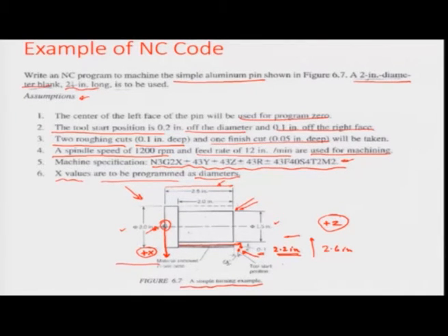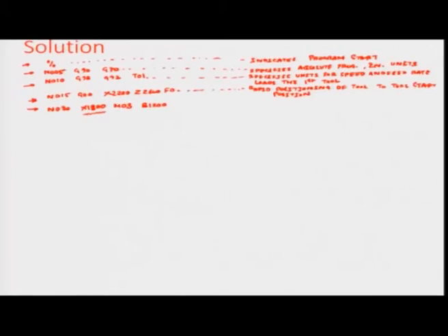So, the tool in its current location goes to 1800 or 1.8 inches, corresponding to the X. Because we are reading in absolute manner, please note that we are merely referring to the coordinates written here without considering the plus or minus, because everything written on the right side and the down side here are all positives. Okay. So, in this position there is no feed given to the tool, so let the feed be 0.